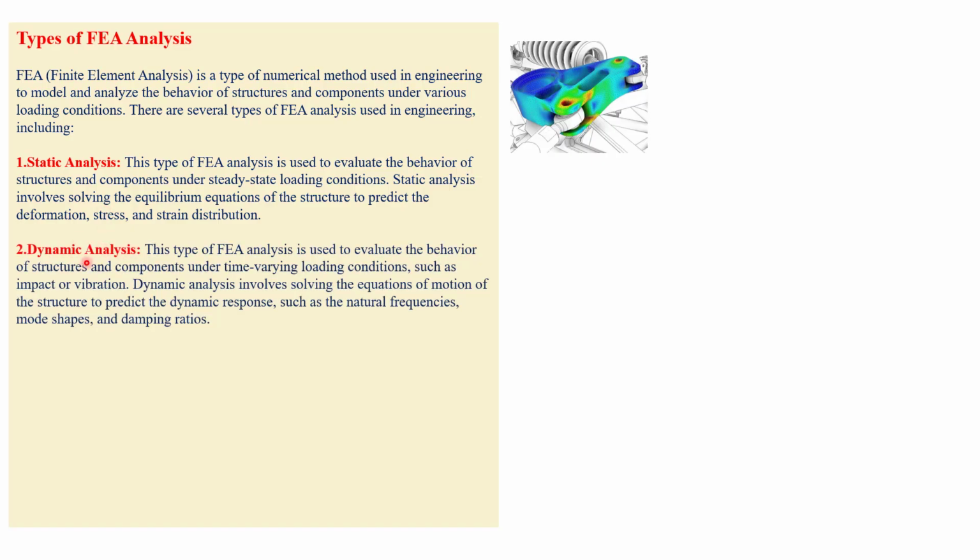This is all about static analysis. The next one is dynamic analysis, which is mostly dependent on time-varying loading conditions. In static analysis the loading condition is steady state, not dependent on time. Here the loading conditions are dependent on time. For example, we have impact analysis and vibrations, which mostly depend on time. We also have natural frequency analysis, modal analysis, damping, random vibration and so on, which are considered under dynamic analysis.